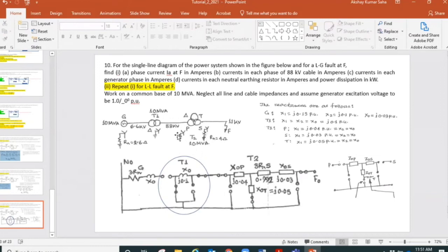If the primary side had a resistance to the ground, then we would have another resistance here. We could have, possibly, because both sides are grounded, star connected. So one side has resistance, and the resistance shown in the diagram is with that side. So it's on the secondary side. If it was also on the primary side, it would come with X0P in series. Does it make sense?